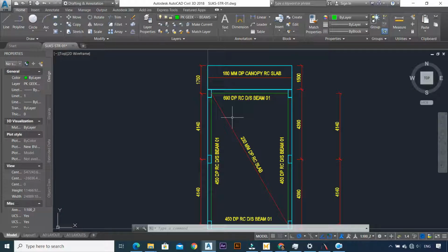It's trial and error. But at the first step, you have to do a preliminary design, which is to take into account some worst case scenarios and some contingencies, right? For you to size your foundation and to see what loads will likely be going to your foundation. You just deal with the worst case possible. And normally it doesn't exceed 10% of the actual value, so you are not really on an over design schedule.